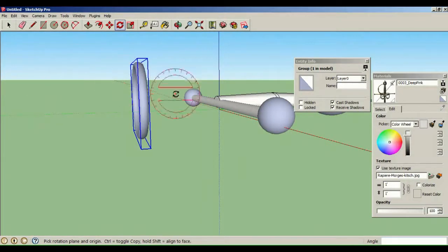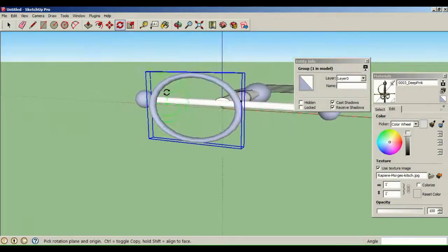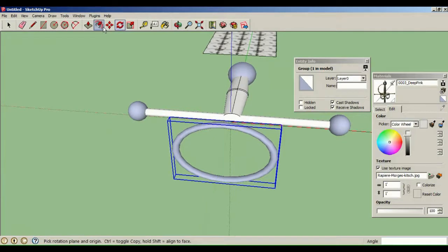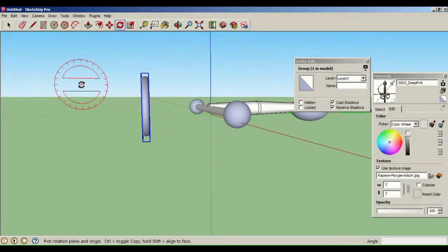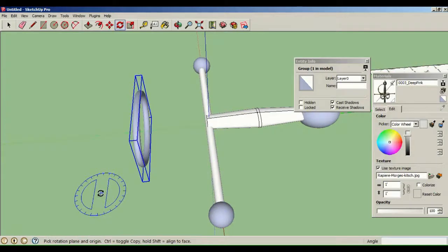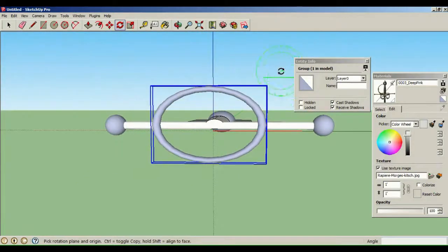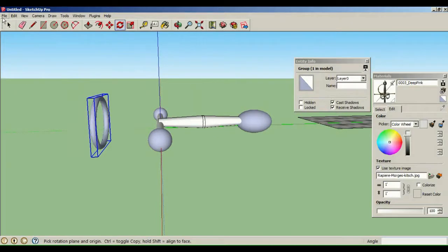Because when you click out here, rather than click on the object, if you click on the object, it'll rotate. As you can see, the 360 protractor is not 100% straight, and it will light red when it's 100% on this face. Because it's not 100% on this face, when you go to rotate it, it won't be rotating the correct way. But now that it is, you want to wait until it's red, or whatever angle you're trying to rotate it, blue, or green over here, and then rotate it.